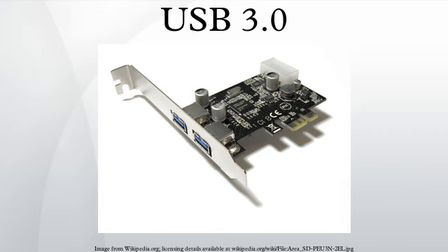Data encoding. The SuperSpeed bus provides for a transfer mode at a nominal rate of 5.0 Gbps, in addition to the 3 existing transfer modes. Accounting for encoding overhead, the raw data throughput is 4 Gbps, and the specification considers it reasonable to achieve 3.2 Gbps or more in practice.